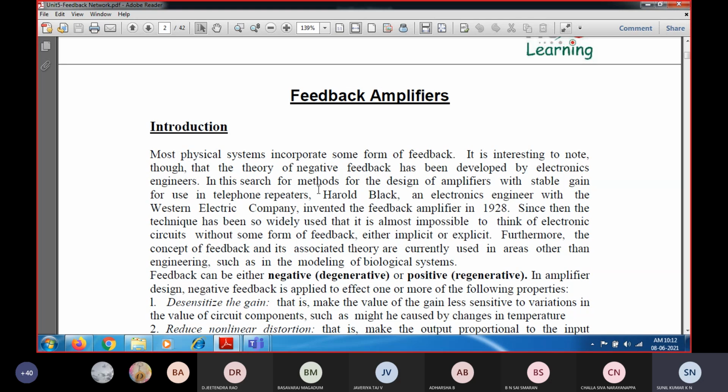The crystal oscillator is going to provide sustained oscillation, and we have seen the electrical equivalent circuit of the crystal. We have also seen the various types of crystals commonly used for practical purposes, that is Rochelle salt, tourmaline, and quartz crystal. Among these, quartz is mainly used because of its low cost, as well as its high piezoelectricity and high mechanical deformation. It lies in between Rochelle salt and tourmaline, and hence quartz is the main material used in digital circuits as well.